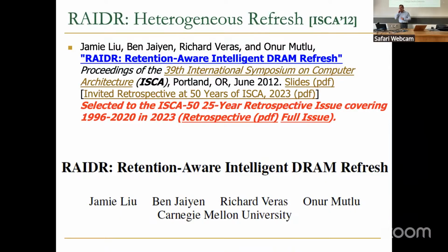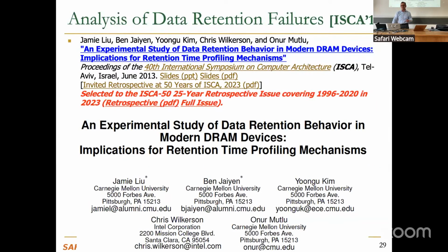But one of the major reasons why we wanted to build this infrastructure was to test a lot of these hypotheses. So in this work, which is one of the early works on memory scaling, at least in recent years, we basically said that there is this heterogeneity in DRAM, and we can exploit it relatively simply. And then we wanted to really test whether we were right. So it's good to have this hypothesis and write a paper that says, if this is true, this is the benefit you would get. And in this paper, which we're going to see later, you can get a lot of benefits by adapting the refresh rate to the cell. So if you don't refresh all cells equally, and refresh the cells at the rate that they need to be refreshed, then we basically said, can we actually make this happen for real? That's why we built this infrastructure. That's one of the major reasons. And we're going to see a lot of these works. This actually enabled a lot of works by us and others.